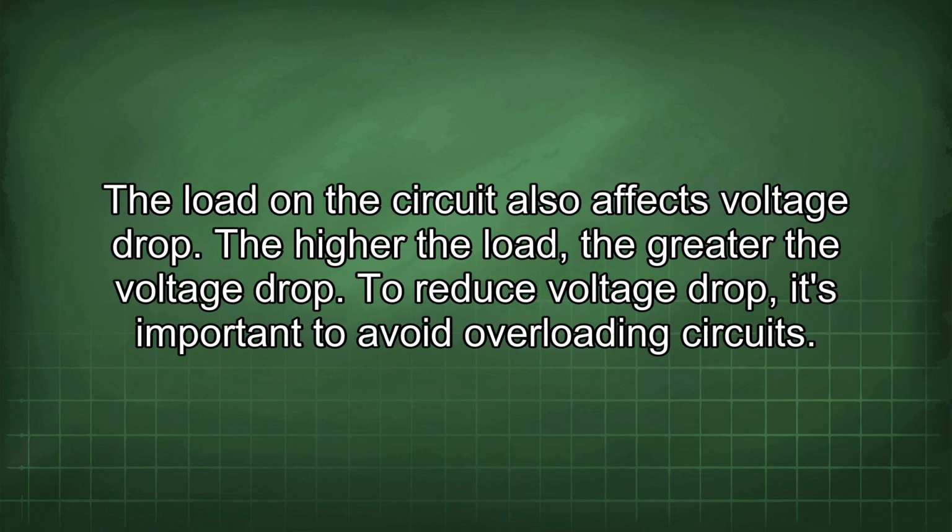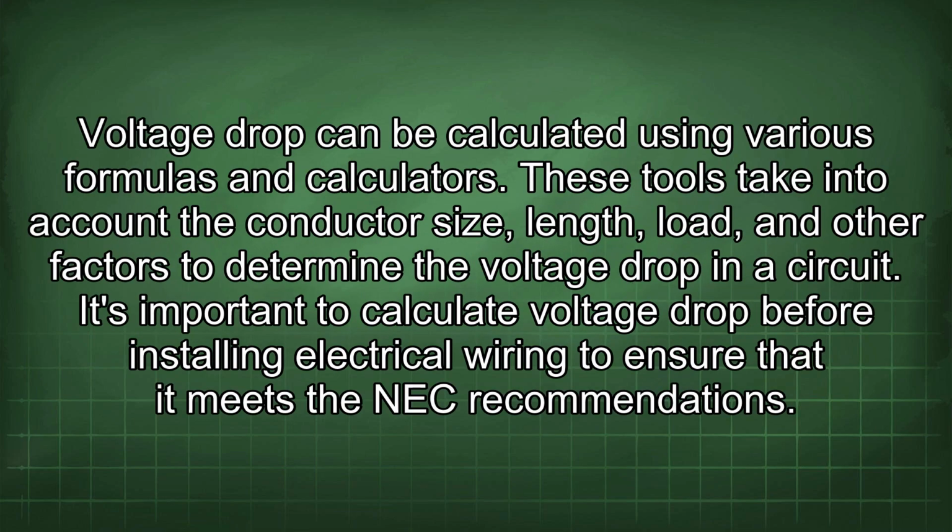The load and the circuit also affect voltage drop. The higher the load, the greater the voltage drop. To reduce voltage drop, it's important to avoid overloading circuits. Voltage drop can be calculated using various formulas and calculators.